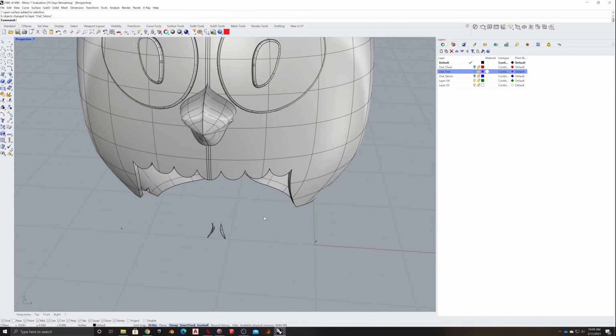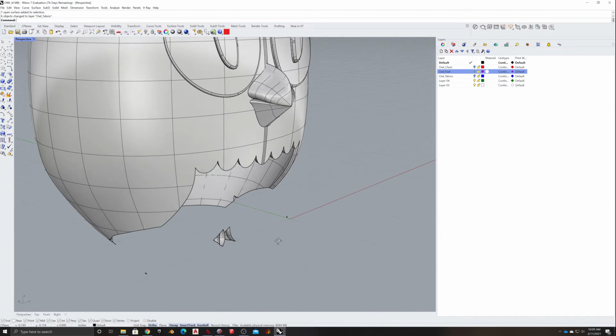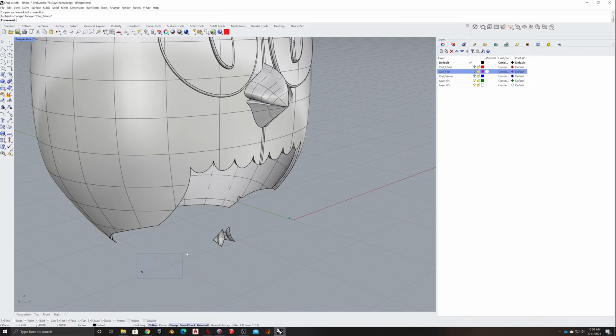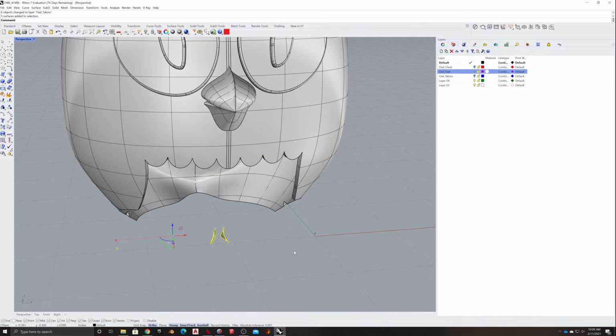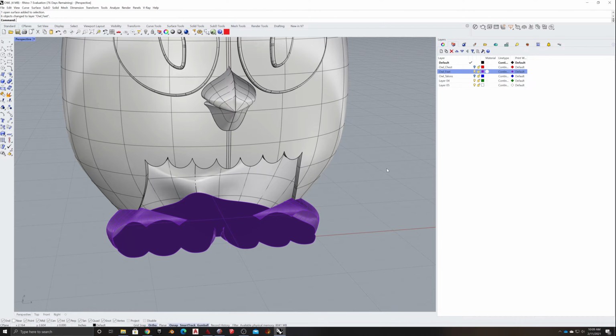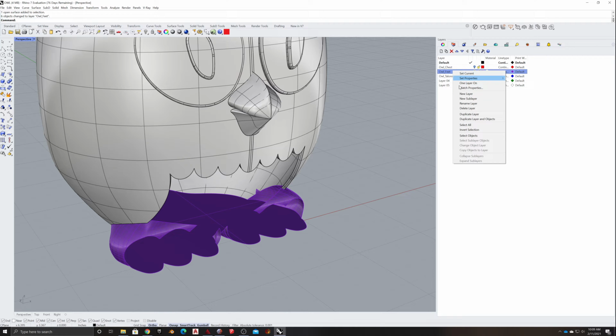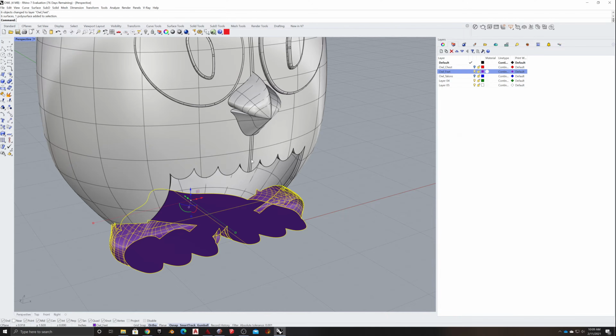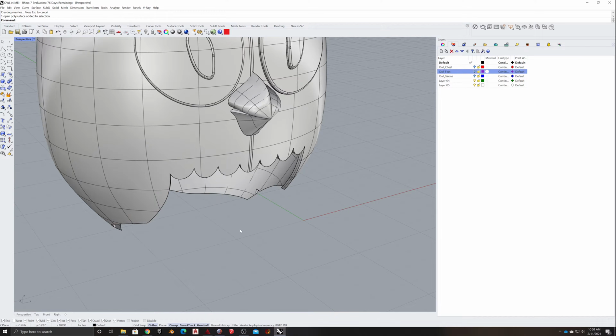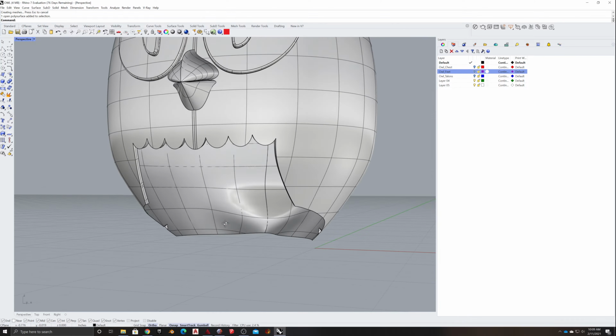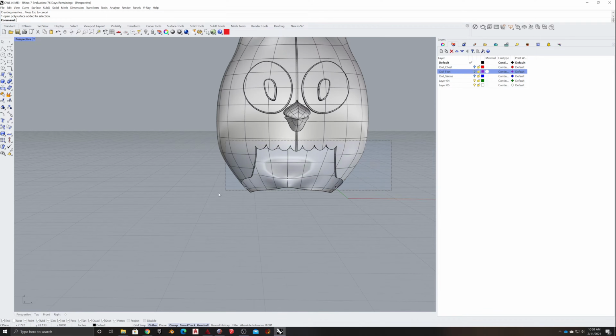Hide this too. And you can see part of the reason why we're hiding stuff is so you can pick up these little things that aren't being hidden and make sure they're on the proper layer too. Change object layer, they'll disappear. Then I'm going to bring this layer back and select the objects on the layer by right-clicking and join it together. So now I'm going to click on one spot here and hide it and just make sure, yep, all those parts joined. Okay, cool.